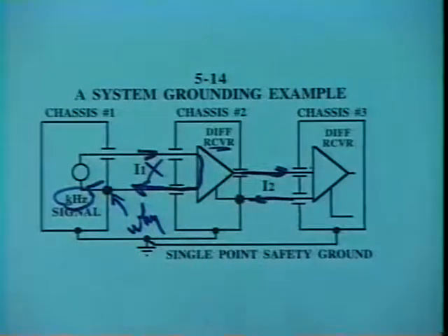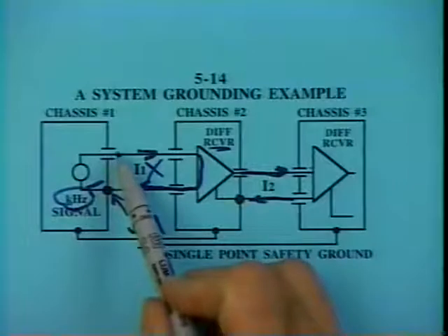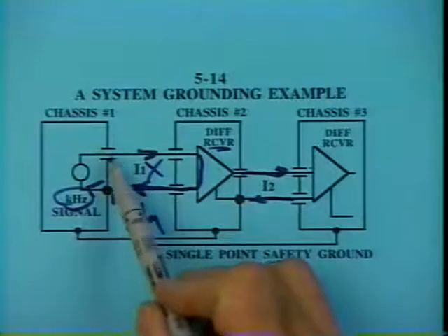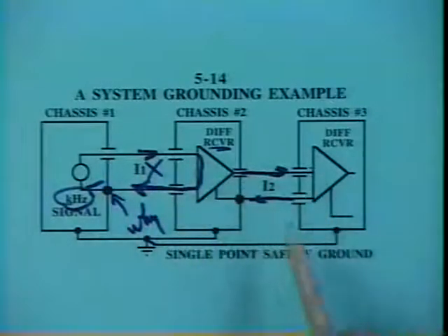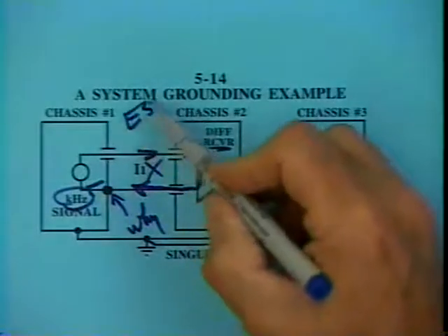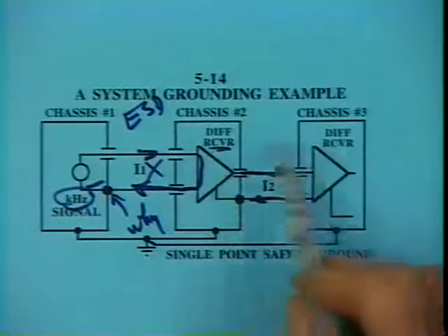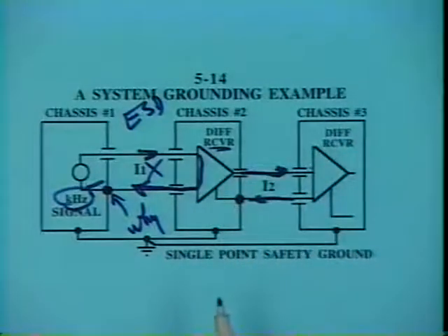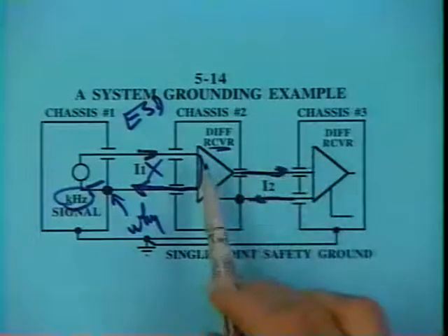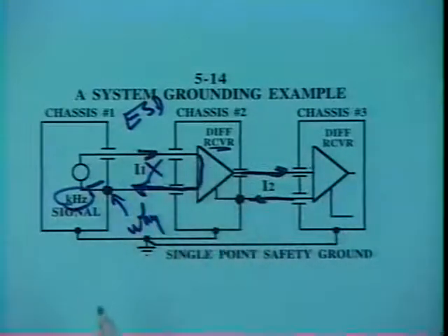But anyway, first we started talking about signal flow, and I wanted to make sure I knew where the signal was located. Now you see we have capacitors showing between the signal lines and the metal housings in all cases here, where there isn't a direct bond. That's probably for, say, a little bit of ESD protection. And also, if some of these boxes happen to have digital circuits involved that are not shown, that's to help keep the digital frequencies from coupling back out on the low frequency wiring. So this type of connection is for high frequency susceptibility and emissions, improving both of those.